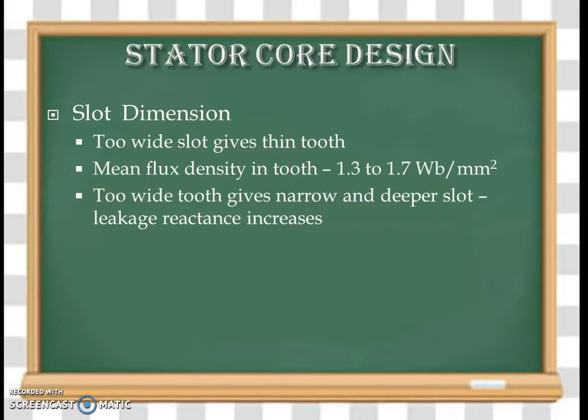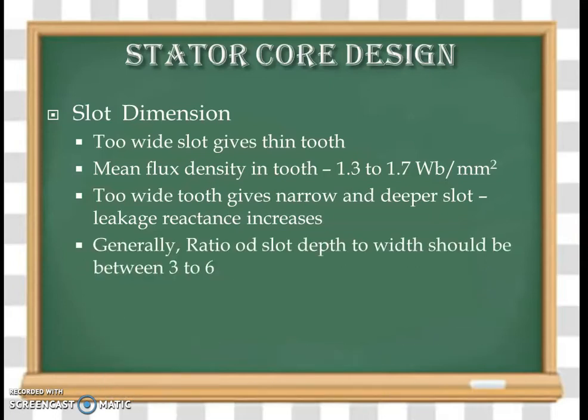So we should not consider too wide a slot. At the same time, too wide a tooth is also not an advantage. So as a rule of thumb, we normally take a ratio of slot depth to width in between 3 to 6. So this way, after designing slot area, we can consider the slot dimension.